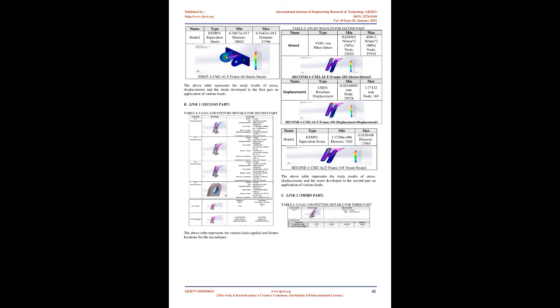Parameters are constraints whose values determine the form or shape of the model or assembly, and inputs may be numeric parameters, like line lengths, circle diameters, or geometric parameters. Numeric parameters are often related to one another through the utilization of relations, which allows them to capture design intent. Design intent is how the creator of the part wants it to respond to changes and updates.